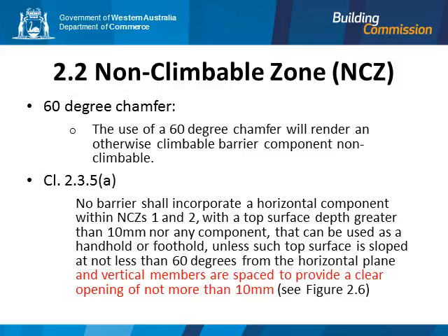Although the standard permits gaps between vertical members of up to 100 mm to use the chamfer, Regulation 15B of the Building Regulations 2012 modifies the standard in this instance and corrects it to apply in a similar fashion to the 1993 edition. I have marked in red the additional text from the regulations, and you may want to add this to the text in your standard.